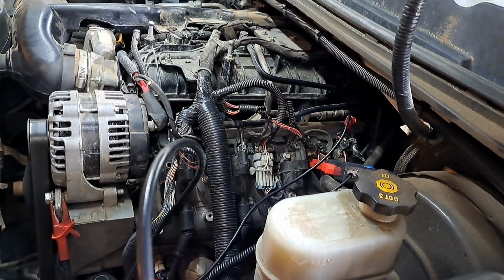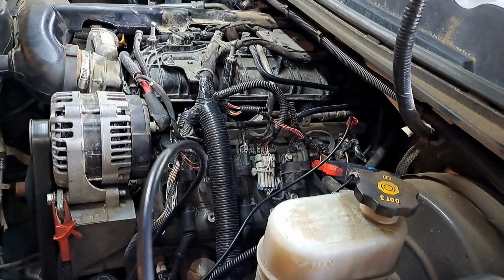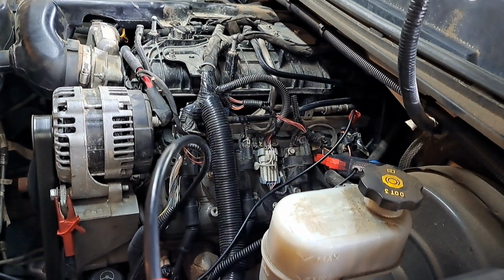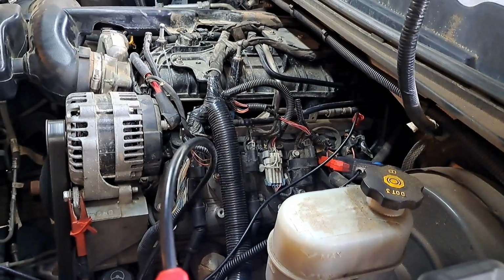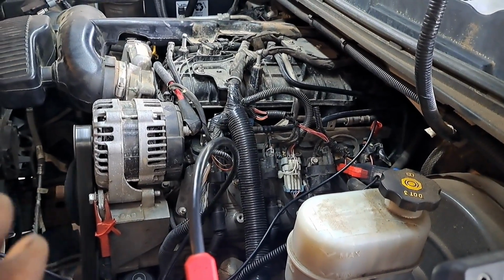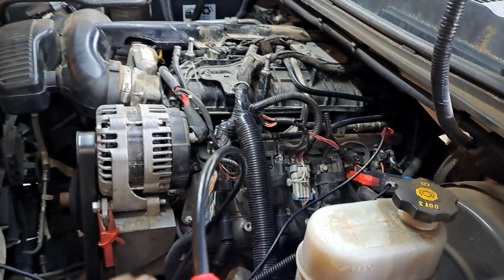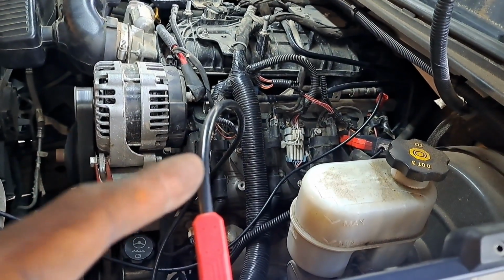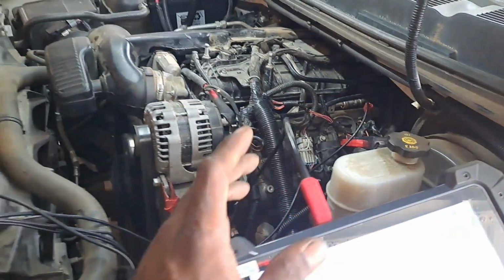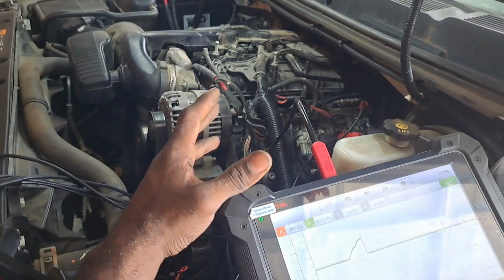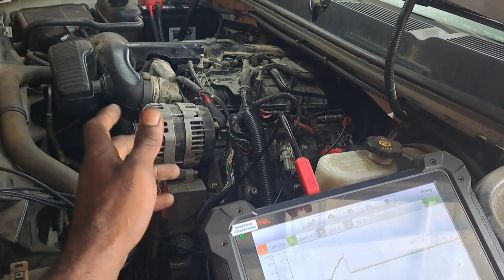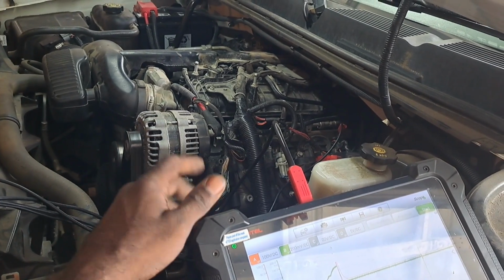But this seems like it's going to be one of those common things where if everybody else had injector problems, replace the injectors. The even bank was the standard. All of those checked out, and they were uniform with this bank on number 1. Just like the solenoid on a Nissan, I can test the amps, the current flow, the voltage, the spikes and stuff, and it wound up being like a weak component.